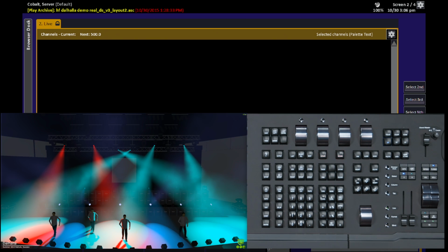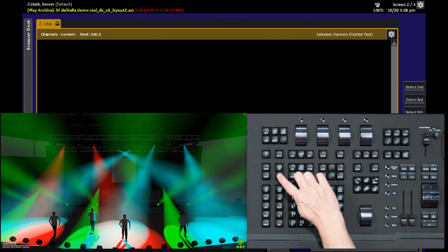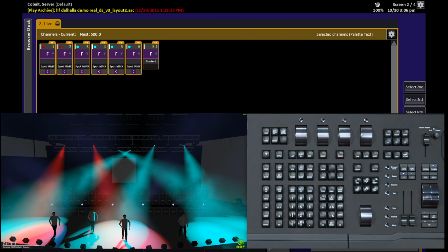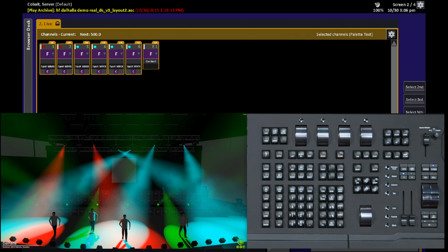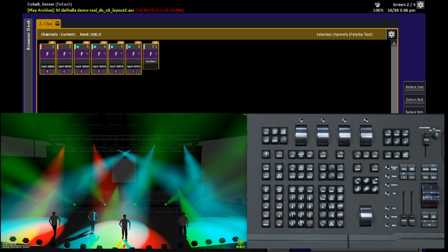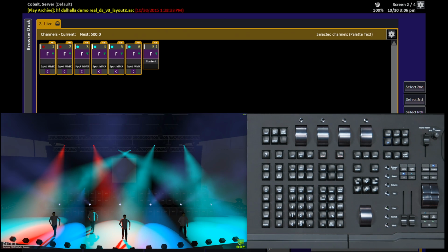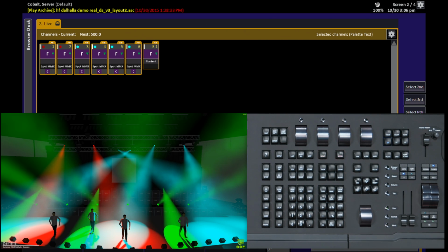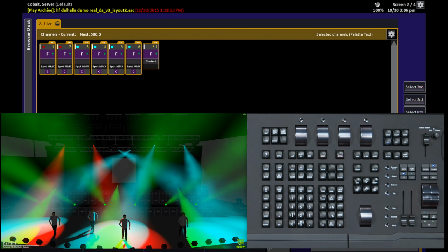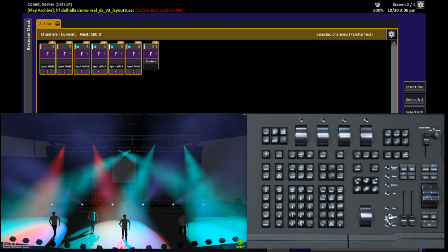When nothing is selected, the Invert Group command will select all channels with intensity above 0, including all effect playbacks that are above 0. This is a quick way to combine those lights that are perhaps running under the effect or running with the effect in one command and then get those lights recorded someplace special like in a group or in a preset.